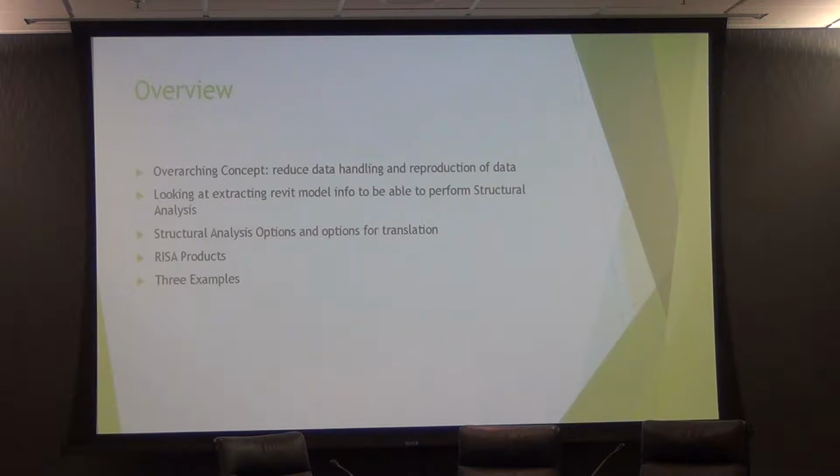And so you sort of come up with a hacked version where you take the things that RISA does well and use that, and then you come up with your spreadsheets or whatever it is that you want to do. I mean, the example that I would give is concrete design. RISA's pretty good at concrete design, but I think that probably there's other software that's a little better at it. Previous places I worked, we basically just do it all with Excel spreadsheets. We actually had written things whereby you could extract the RISA forces and data, but then we would run our own batch routines to come up with our reinforcing layouts and things like that.